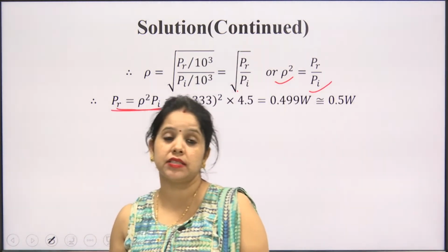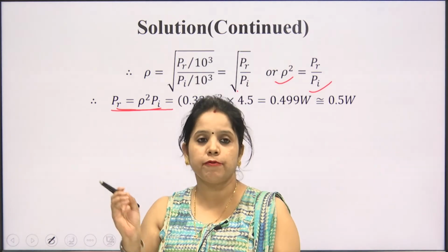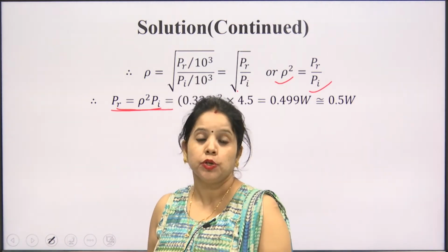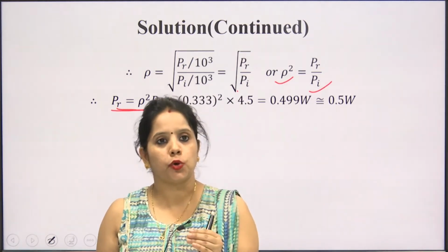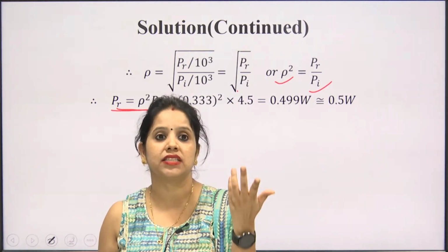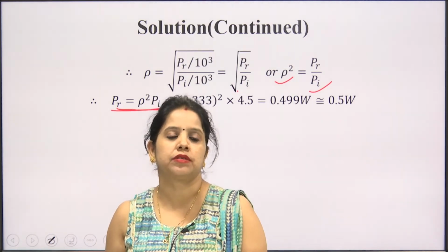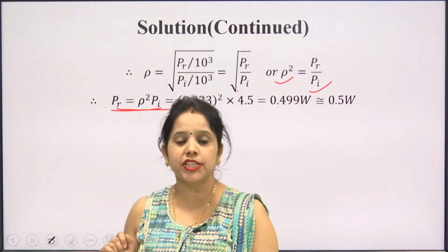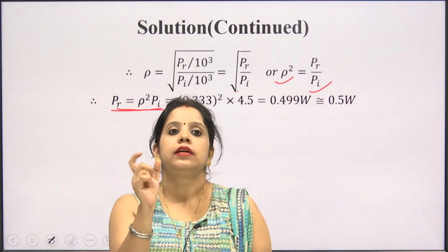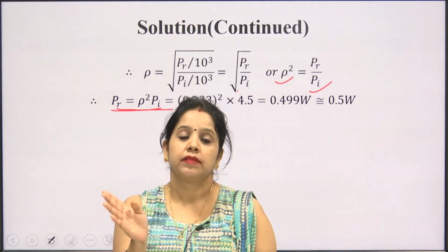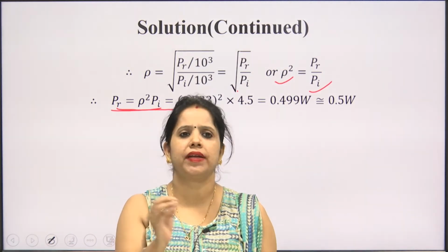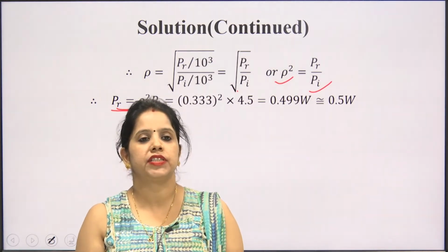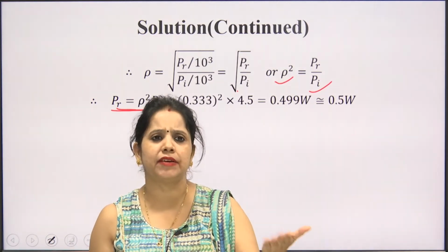So, for solving this equation we have to solve one by one all the parameters which are required for getting the final expression. So, for all the microwave measurement questions, numericals, you have to first analyze which type of devices are used, and then only you are able to get the correct measurement. So, in the first case we have the difference between the two distances, that is d2 minus d1, available in the given parameters. So, we can easily analyze that it is a double minima method.